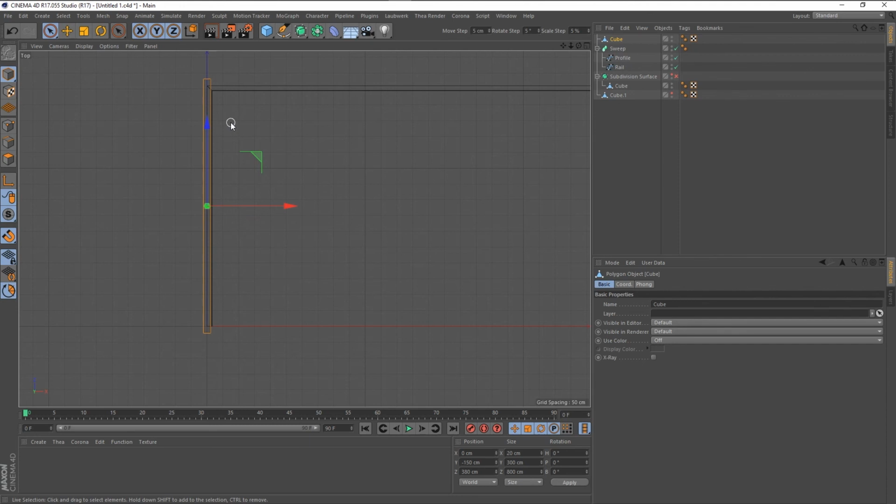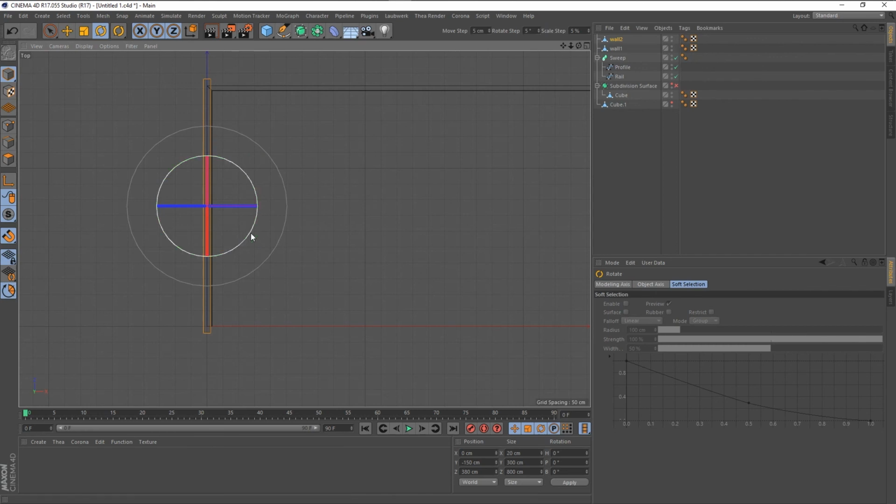And now if I want to create another wall, quick way to do it would be just to Control click drag on that cube, and we call this wall 1. So I double click on the name to change it, and we'll click on here and call it wall 2. Hovering over the view, I didn't click in the view or anything, just hovering my mouse over the view, hit R for rotate, click and drag in on here. If quantizing is enabled, it should be snapping like that. You don't have to hold shift or anything.